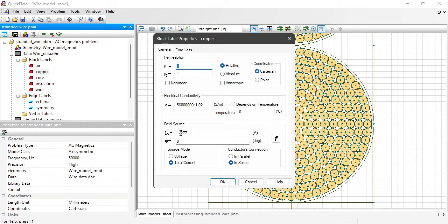So I specify current 1 ampere divided by the number of strands. The transposed curved wire features greater length compared to non-transposed solid wires. So naturally the transposed wire has higher DC resistance, about 2%. We take this into account by attenuating the conductivity.